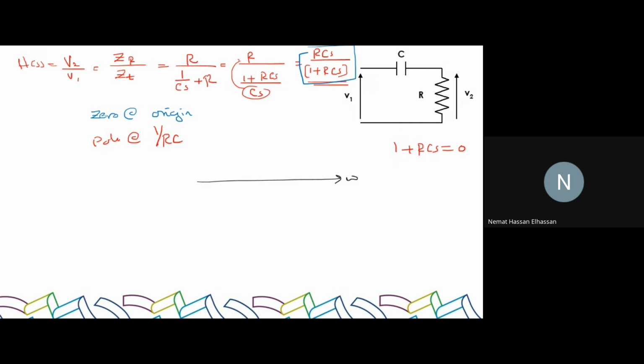We have the frequency, we have the gain in decibels. Let's plot the 0 at the origin. Now, previously you said that zeros and poles, the way we plot them is exactly the same, except at the break frequency, zeros will be increasing in gain. Poles will be decreasing in gain. But we have one special case, which is if the value is at 0 at the origin.